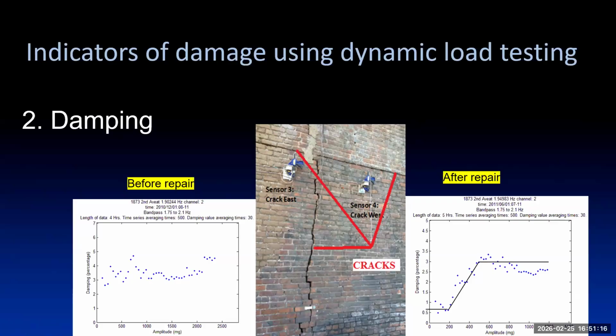And then a high amplitude plateau, which is caused by all those things that I showed you in the scanning electron microscope, everything has given its entire capacity. There's also a reduction in damping at very large amplitude, and this has been shown by Professor Yukio Tamura in Japan as well. So the Japanese are changing their code slightly to say damping will decrease with very large amplitudes.